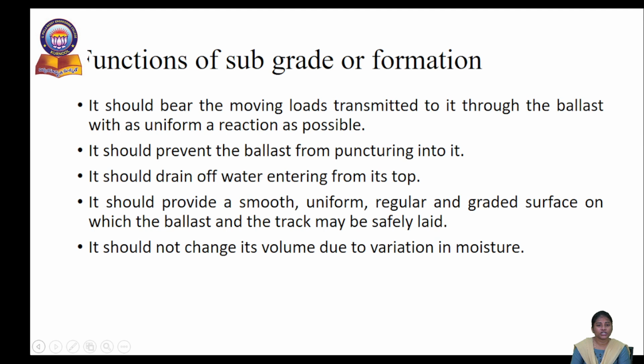So what are the functions of this subgrade or formation? Ultimately it receives all the loads coming from the rails, sleepers as well as ballast. That is the main function of the subgrade or formation in the railway track. There are some other functions. It should bear the moving load which is transmitted to it through the ballast with as uniform a reaction as possible. It should prevent the ballast from puncturing into it.